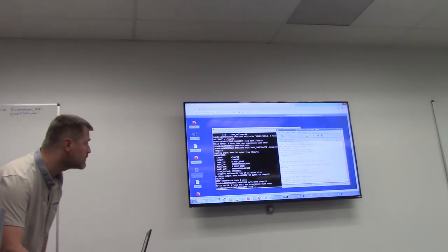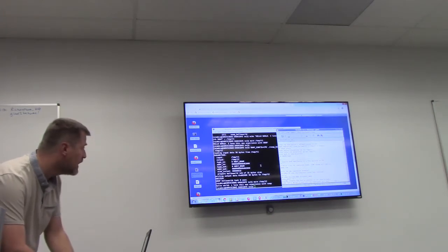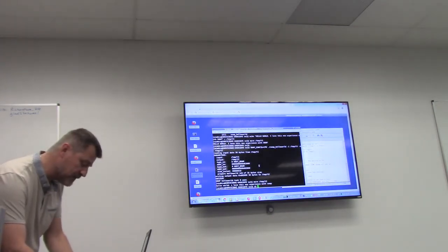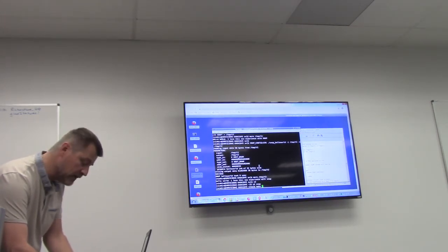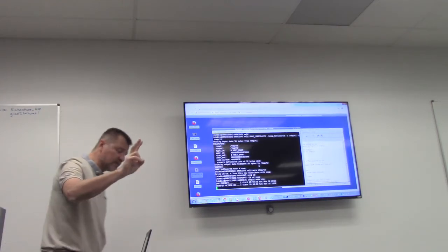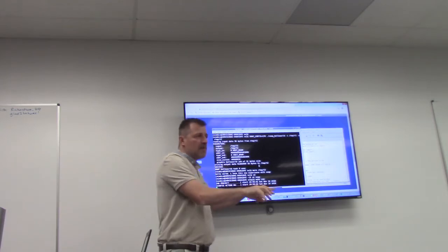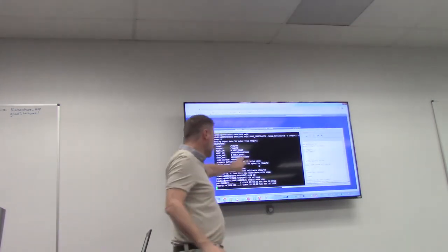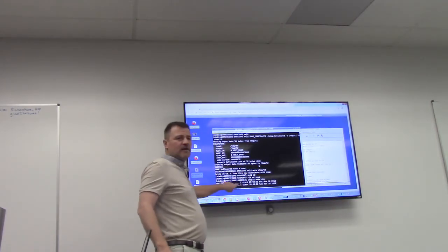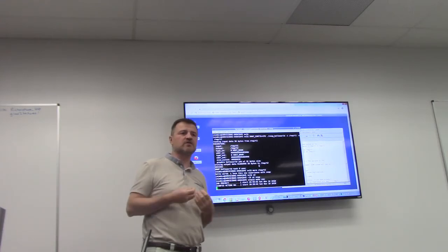Now, what we want to do is come back to Snap, and we will make sim. So cd snap, whatever you want. And now I do make sim. Make sim is doing two things. The first one was a make, the second one is make sim. If you type make, you have the list of the options. Make sim will make model, and make model is preparing the minimum hardware for the simulation to work.